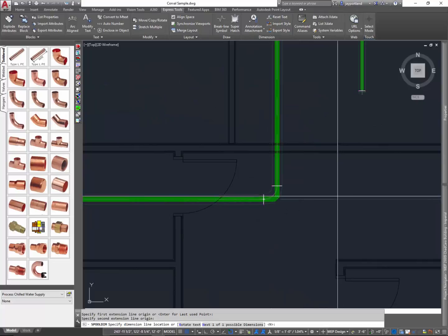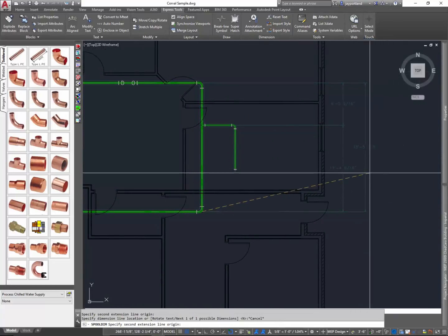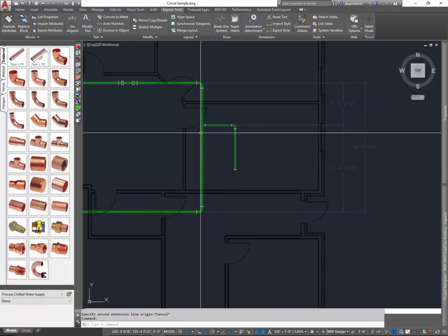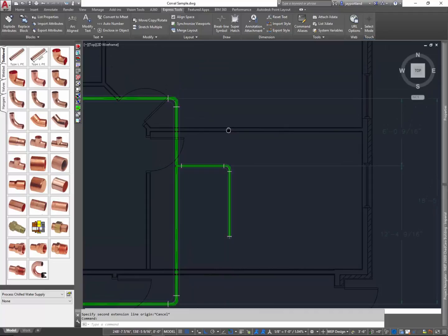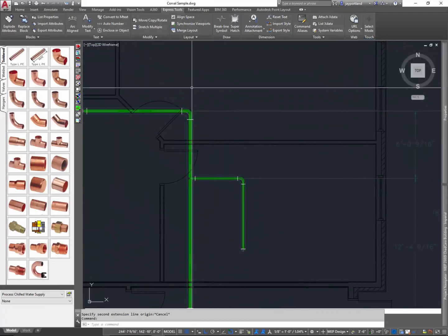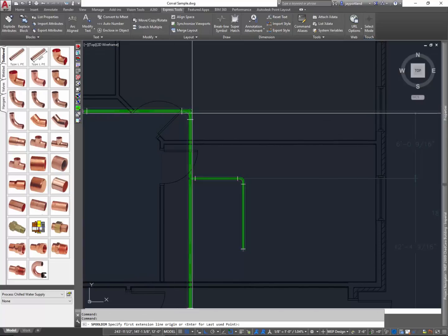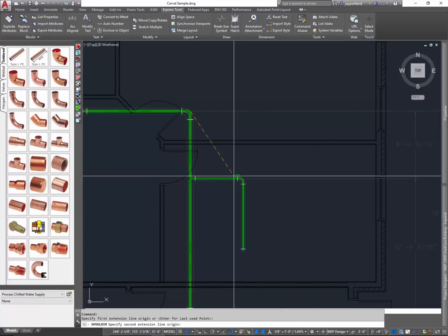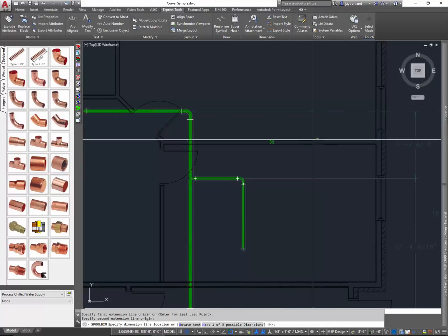and earlier you saw me go from center to center here. So I was able to put that overall dimension here, as you can see. But now I can go end to end. So let's do a couple of interesting dimensions right here. So I'll just use my SpoolDim command. I'll go center to end if I wanted to, right? So that's my center to end.